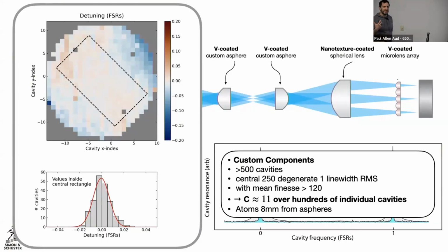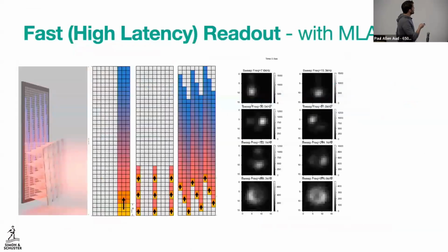But what I wanted to say is that this idea that you should be thinking seriously about micro lenses and micro mirror arrays all over the place, I think the opportunities are quite broad. We've now put a micro lens array in front of an EMCCD and imaged during our readout of the EMCCD. And then what you can see is that you can tilt this micro lens array such that each row of the EMCCD is only exposed to 1 pixel in your image.